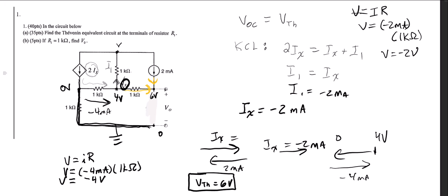And so everything up until where I get to an element is all at the same voltage. Anything that's connected by a conductor is at the same voltage. And if there's no current flowing through it, then it's not going to change the voltage. This resistor's not doing anything. So since I made this ground, that was also going to be 0 relative to ground. Really, what I know by doing Ohm's law is that this side is 4 higher than the other side.